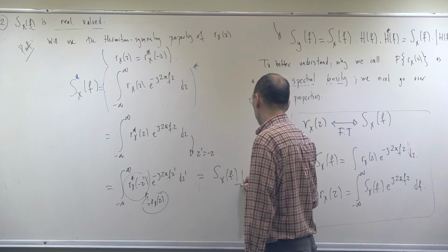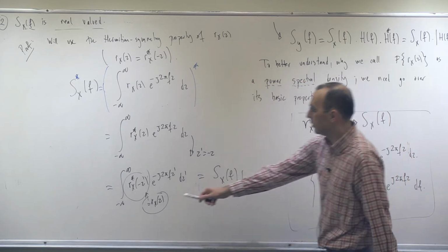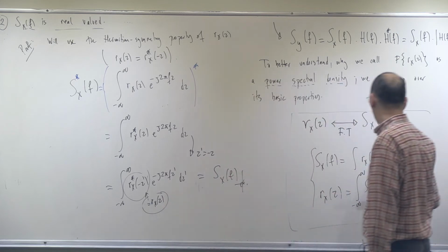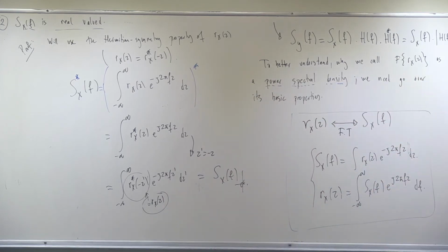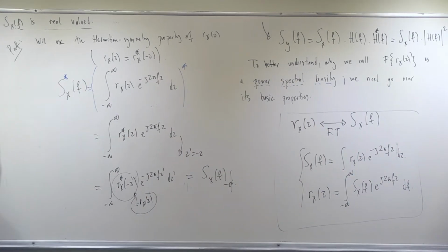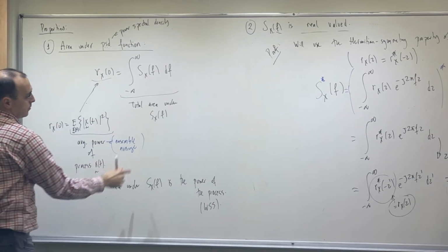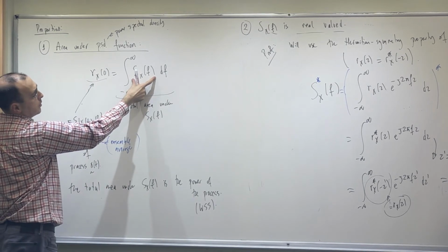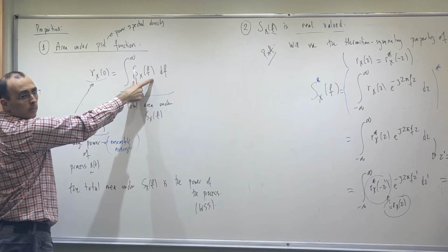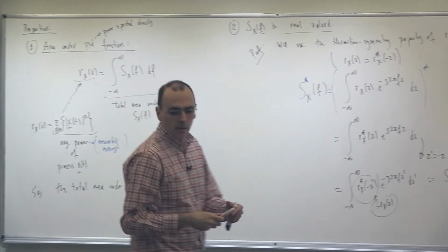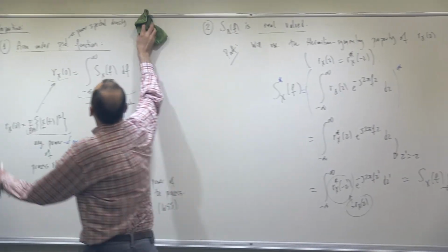So this is the end. Because this is nothing but the power spectral density definition: Fourier transform of autocorrelation, as we did over here. So it's a little bit interesting. Now, the area under this function is equal to the process power. Furthermore, this function is always real valued. There are no complex numbers involved. But I need more. So one more thing.